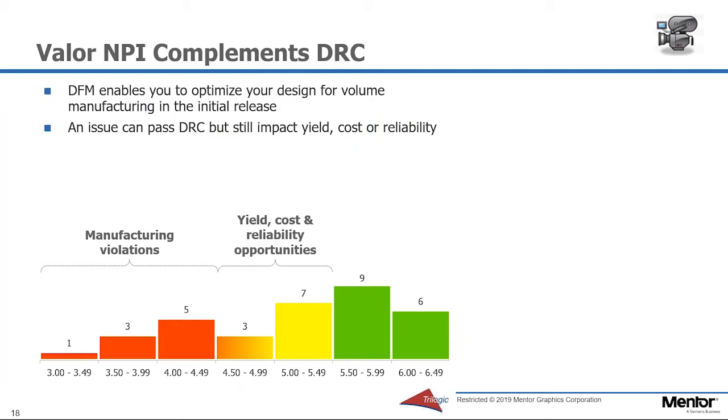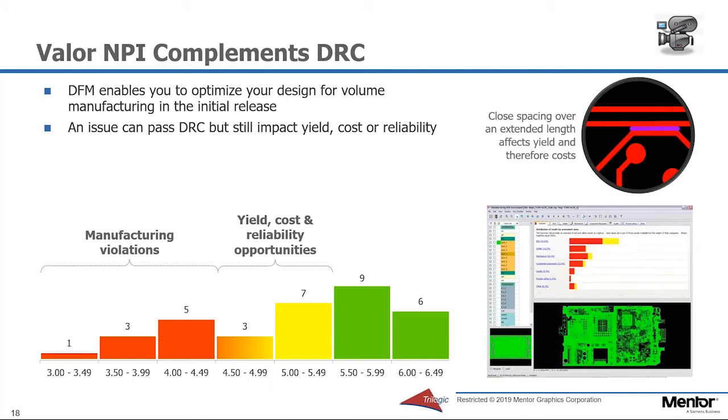The MRA is our main tool to facilitate the review of any number of analysis results, and it does so by grouping them into assessment areas. Each area relates to a specific fabrication or manufacturing problem or process. A summary pane provides an overview of results of all assessment areas and categories. The MRA can be used to sort and review analysis results, isolate issues that will most affect quality and yield, define groups and run analysis actions, and report issues of interest.